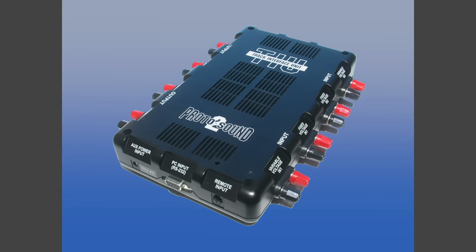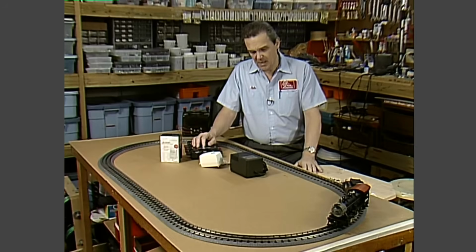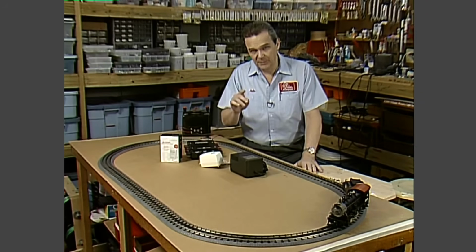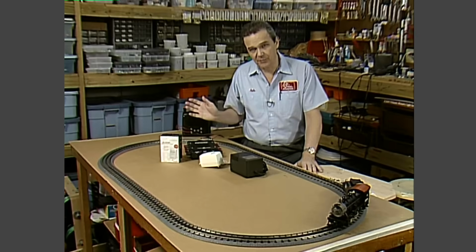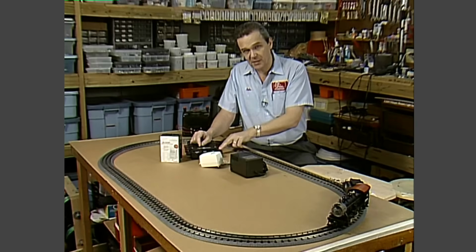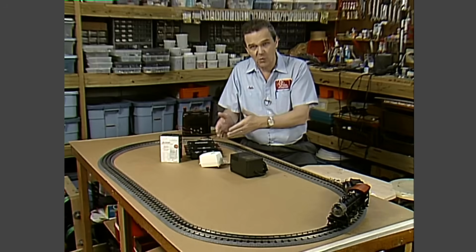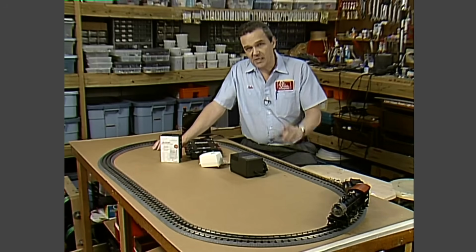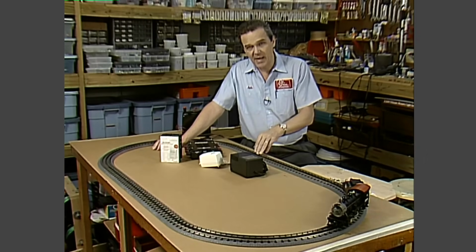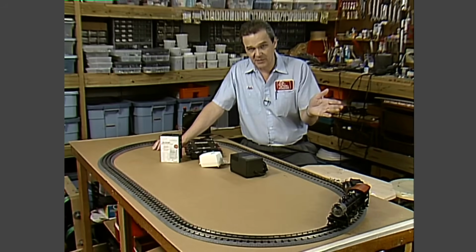It's a good idea to power the TIU with a separate power supply for several reasons. Let's say you're running trains using the fixed in 1 channel and you have a derailment that creates a short and trips the breaker in your transformer. If you're powering the TIU via the fixed in 1 connection, the TIU shuts down when the breaker trips because it's no longer getting any voltage from the transformer. If the TIU shuts down, the DCS signal is no longer being put into the track, so you have no control over the other engines that may be running on the layout at that time.